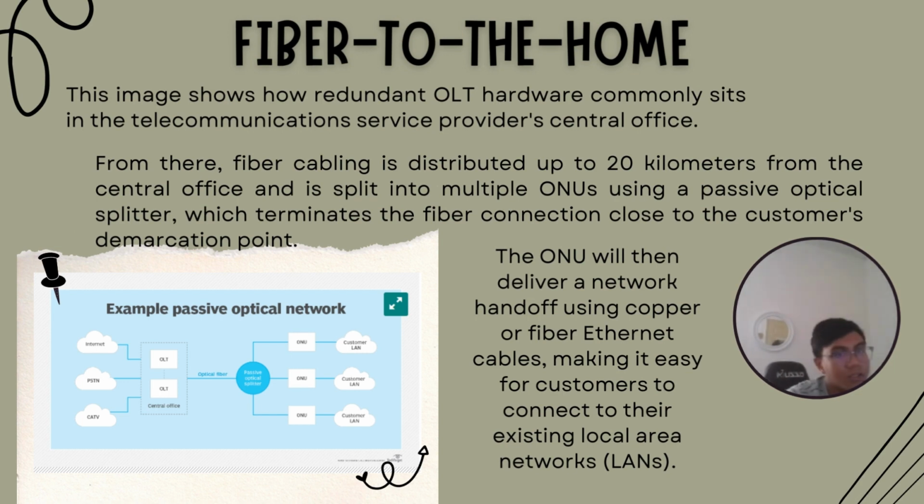So how does a passive optical network work? A PON system consists of an optical line terminal, or OLT, at the communication company's central office and several optical network units near the end users. Typically up to 32 ONUs can be connected to a single optical line terminal. The word passive simply describes the fact that optical transmission has no power requirement or active electronic parts once the signal is being transmitted across the network.